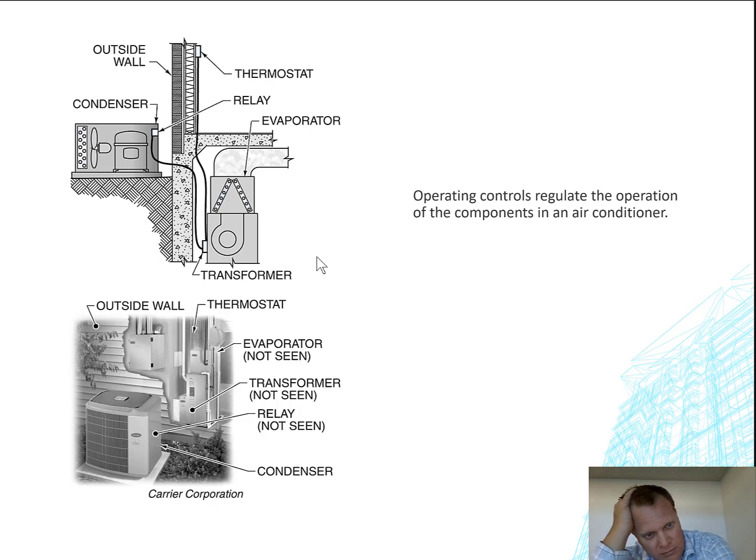Water? No. There's no potable water being supplied unless we had a humidifier in there. So if we had a humidification section in here, we would definitely need water. And in Utah, that's pretty common in a home because it's dry. And the cooling section of your forced air unit is actually dehumidifying the air, so it's making it even drier. And so water, for sure, it's possible on a residential unit to have some water.